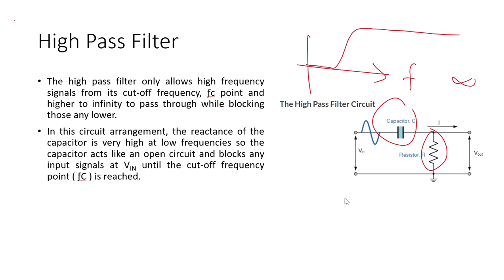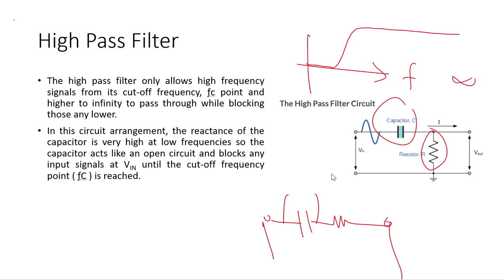As we spoke earlier, we had the same structure, but we took output from this side and gave input to this side, and now we are taking output from this one, so that makes it a high pass filter. In this circuit arrangement, the reactance of the capacitor is very high at low frequency.